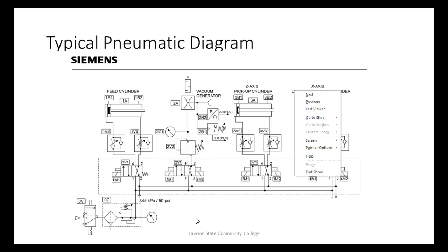The problem we have with actuators is long strokes. What is a stroke of an actuator? How far it can extend, right? Well, the problem is if I needed 12 inches of extension, that means the cylinder itself would have to be bigger than 12 inches, right? You understand? And then I'd have 12 inches out this way. So that means this sucker right here is going to occupy 24 inches worth of space.